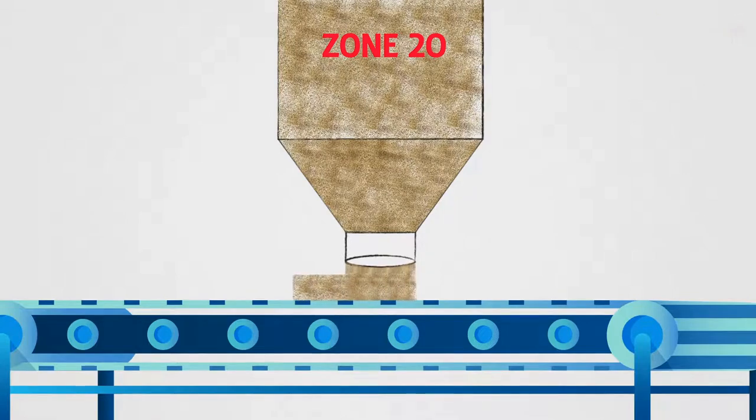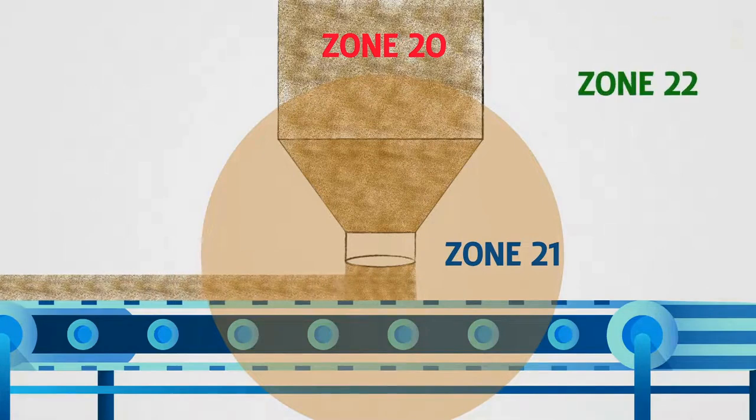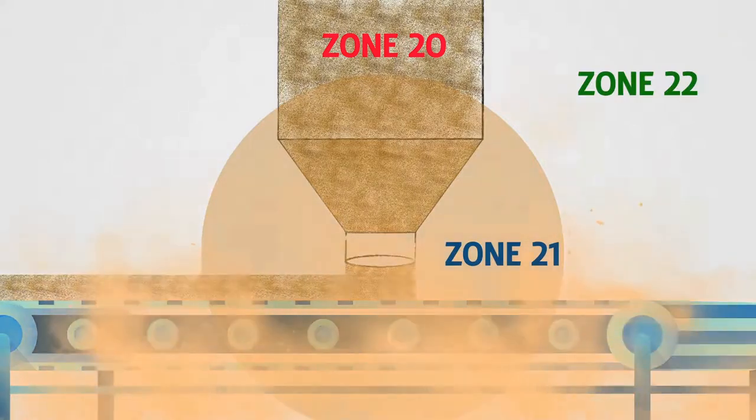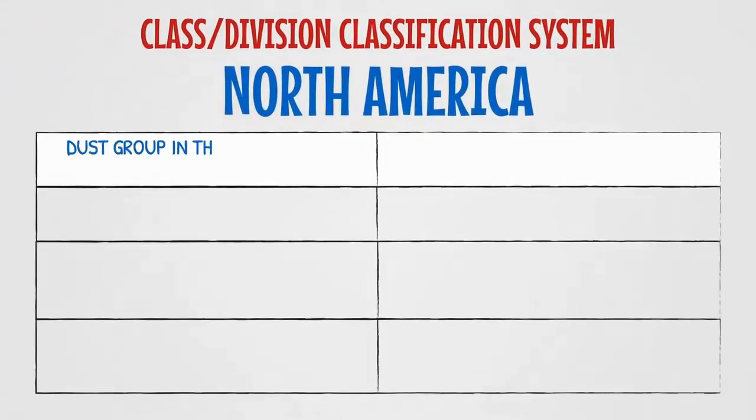In our graphic, dust is allowed to drop from the container onto the conveyor below. The path taken by dust that is allowed to be released from the container when required, called a primary grade of release, creates a Zone 21 environment. Unintended leaks from an incorrectly fitted dust-tight container lid or accidental spillages, called a secondary release, create a Zone 22 environment, as we can see in the graphic. Electrical devices installed in any of these three areas must comply with the requirements for Zones 20, 21 and 22, respectively.